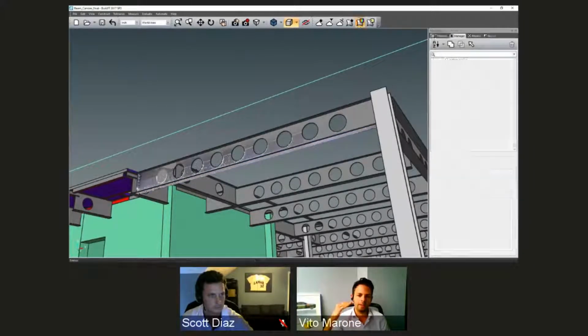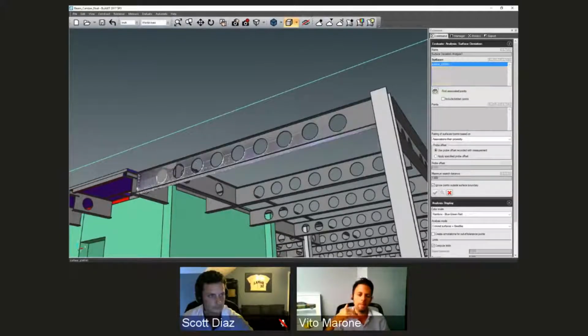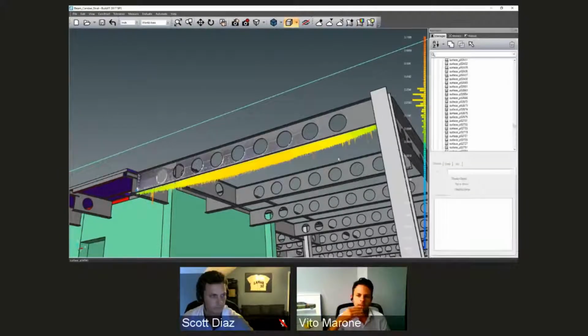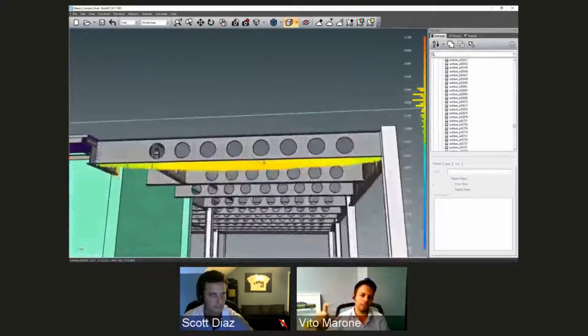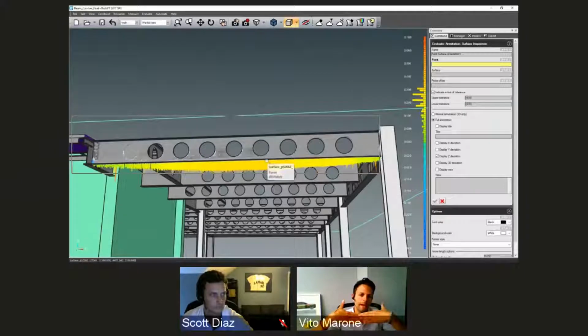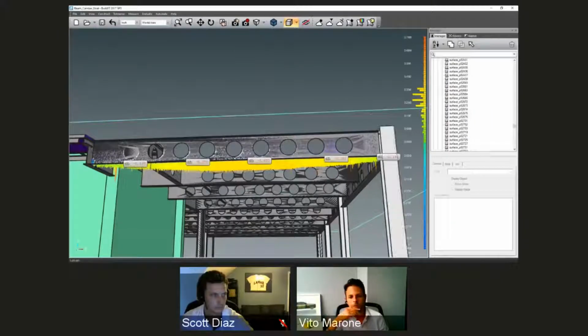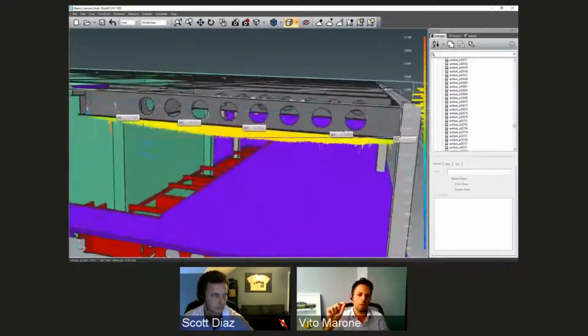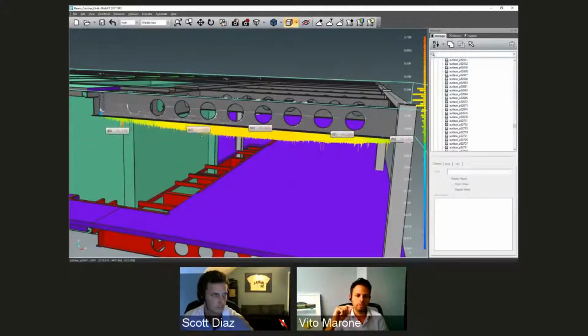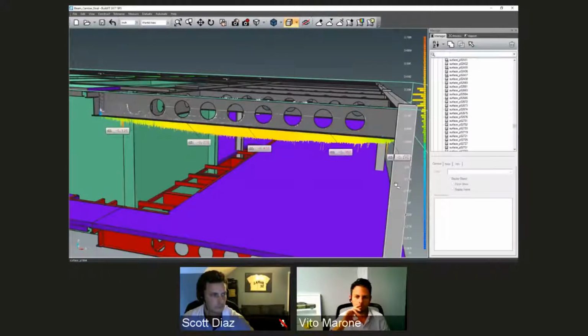So we're taking the point clouds and analyzing them against the surface of the beam. And again, we're going to get a color map and needles that show the deviation of how much it's actually bending. So you're getting a color map of where it's at, and then you can take specific queries at different points of the beam. It's very visual.